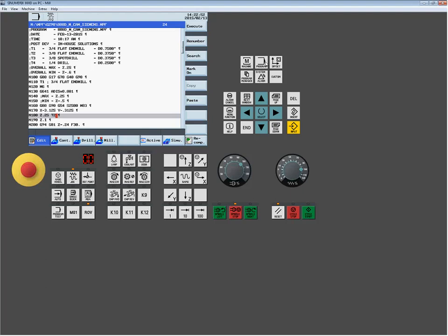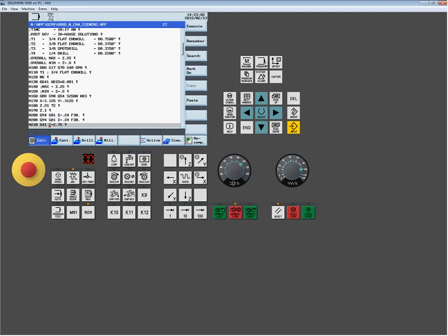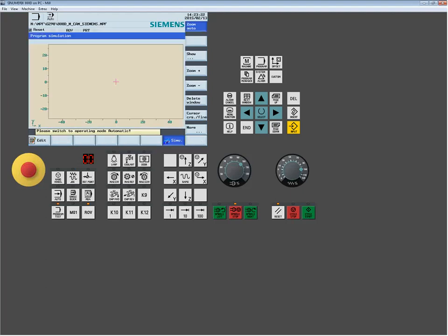So we're going to run this program, and then we're going to try a couple things, and we're going to notice that nothing's changing. And then I'm going to show you kind of what's happening here. But these are the things you're going to start to have to deal with when you're dealing with post processors, especially debugging them. A lot of times it's designed for one machine or one control. You're trying to apply it to a little different machine that was set up differently, and you may get two very different results.